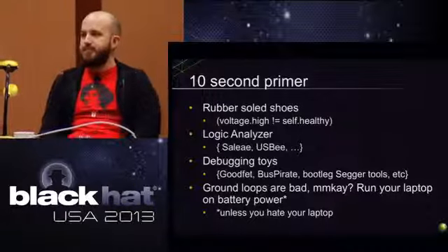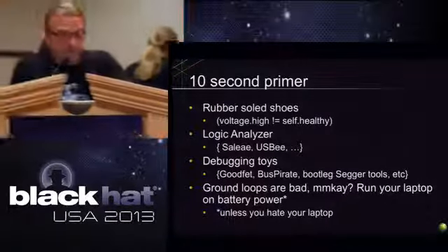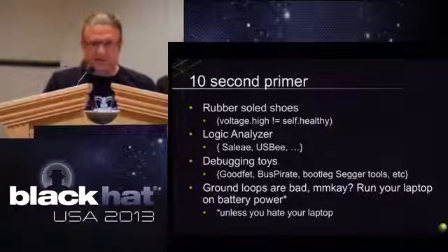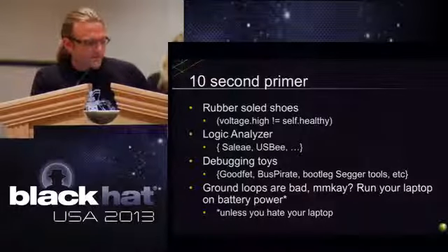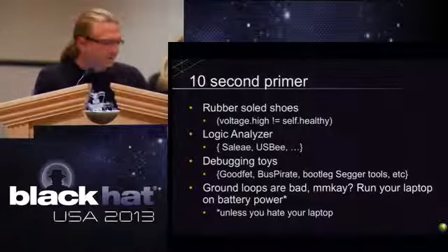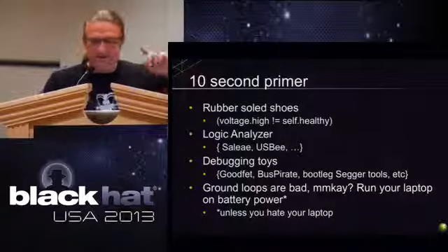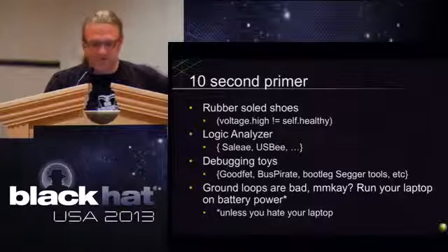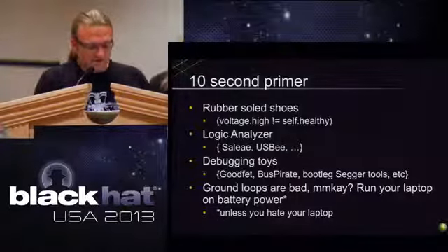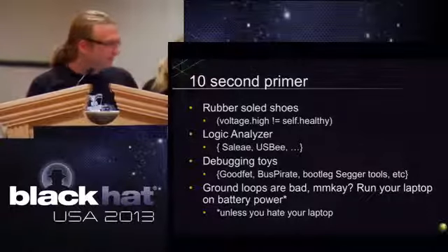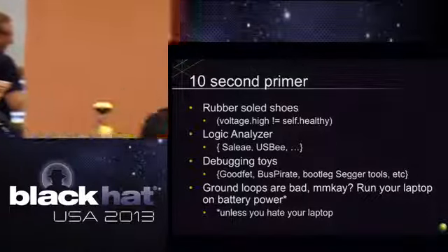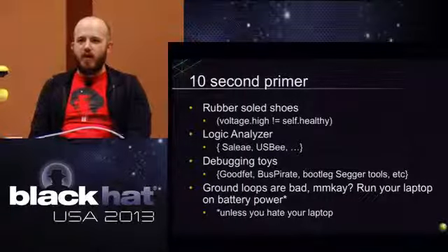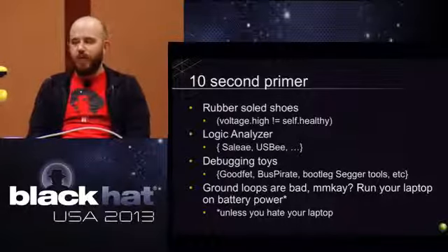And the last pro tip that we've got before we really get into the meat is, if you're working on high voltage or typically almost any embedded system you see, if you are powering that device and you're running ground on the same plane that you're running your device, like if we're running 110, your laptop doesn't like that and you end up doing things like frying your USB ports. If PCBs were designed correctly, that would never be a problem. But when you get into debugging interfaces and stuff like that, there's a couple of them out there that are known for letting you electrocute yourself or fry your laptop.